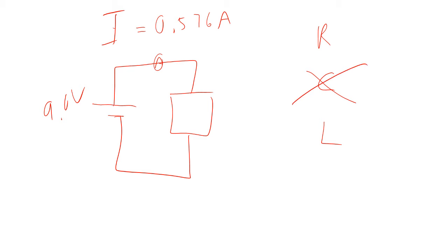You've ruled out capacitor because if this were a capacitor, once it's charged up, you would have zero current. So that means there's no capacitor in series. So this may be an RLC circuit, but it's got no C in it. So it's just an RL circuit. So at best, I mean, it may be just a resistor. So what you do is you want to find out what it is.